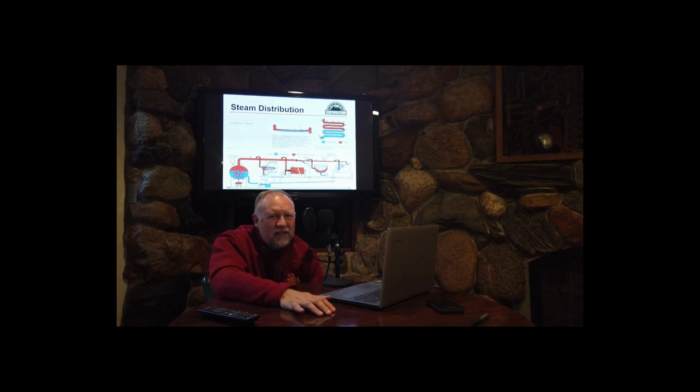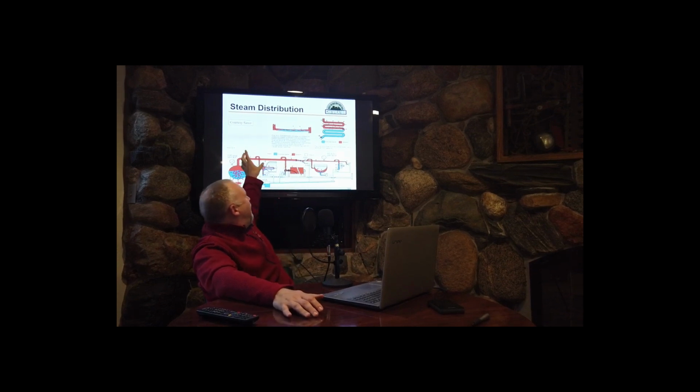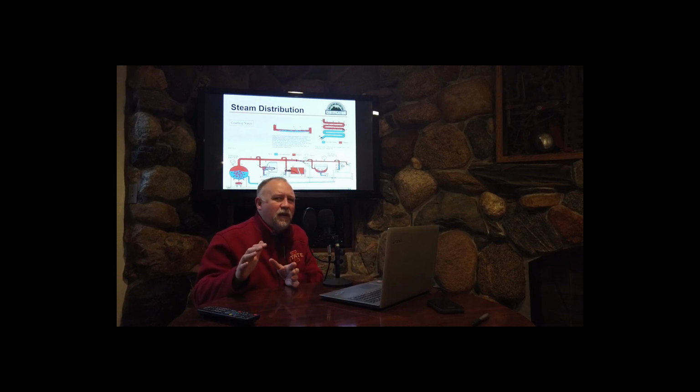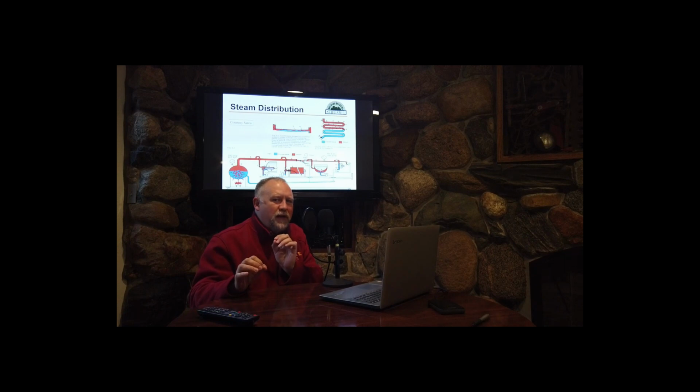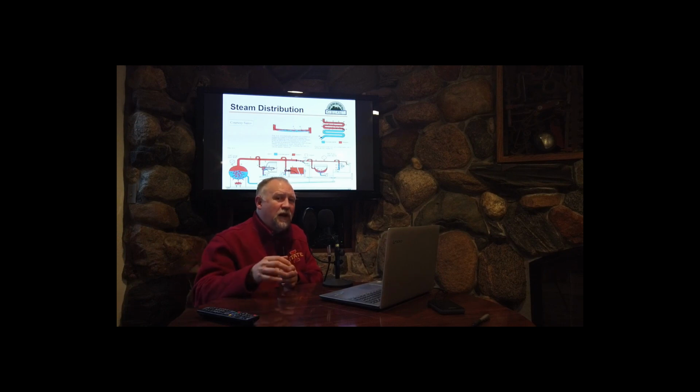Let's talk about that for just a second. If we've got water in the bottom of this pipe and hot, fresh steam running over the top of it, what is going to happen right there? I've got water, I've got steam. The steam obviously has more potential energy than the water. They're going to exchange energy. That steam is going to try to heat up the water, and the water is going to try to cool down the steam. I'm going to get steam condensing, but as fresh steam comes over it, I'm also going to get water flashing to steam.